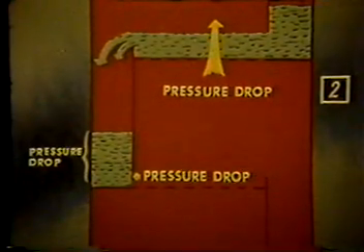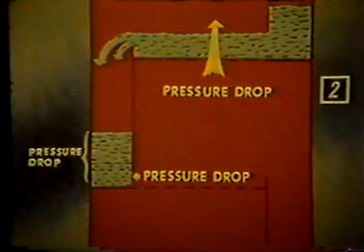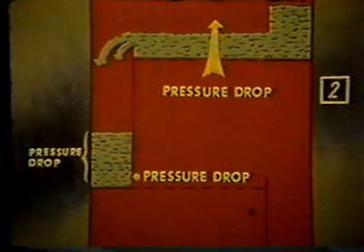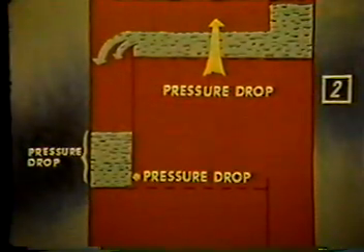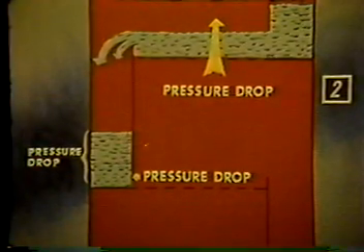This causes the liquid to back up in the downcomer, since the vapor force necessary to overcome the tray pressure drop will also be restricting the liquid leaving the downcomer. Tray pressure drop is a function of the tray geometry and the vapor and liquid rates. And three, the head loss due to the flow of liquid under the downcomer. This is a function of the geometry of the downcomer escape area and the liquid rate.